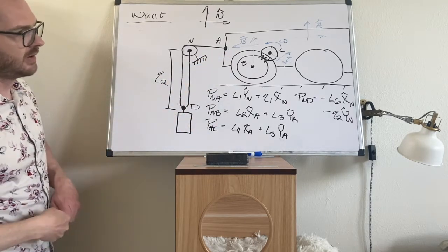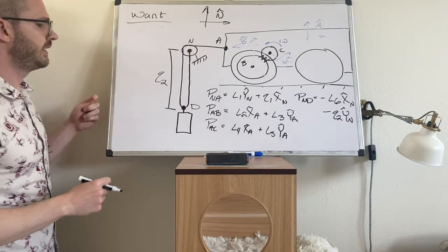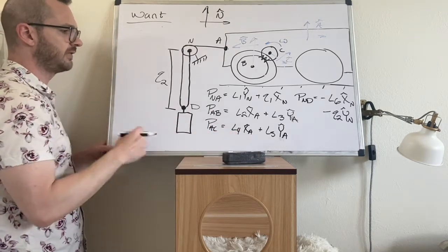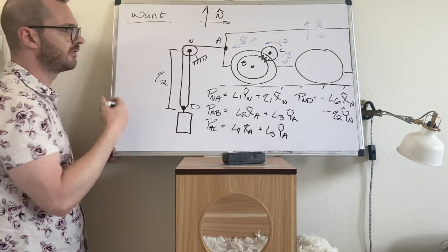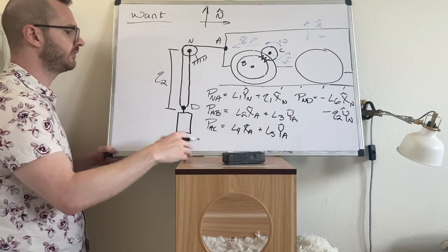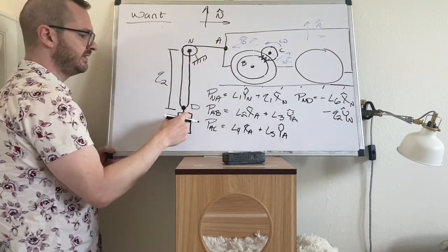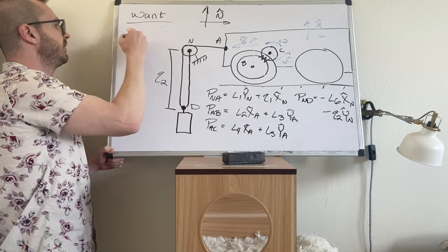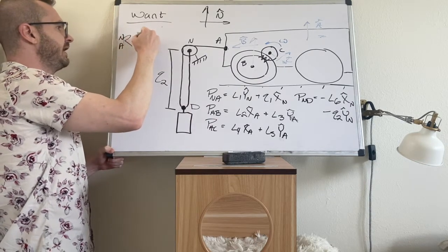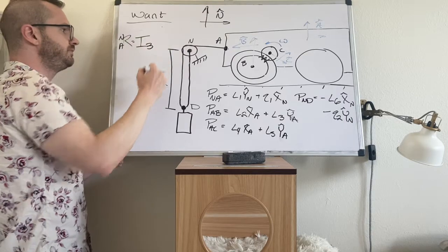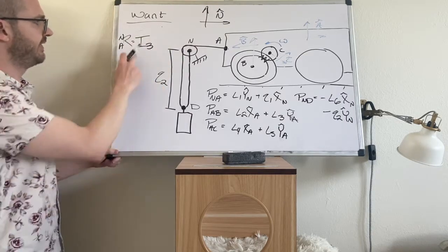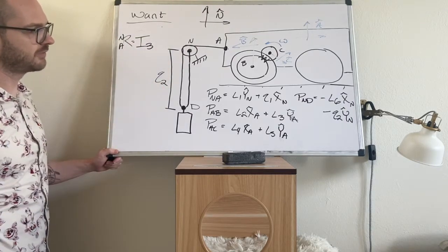All right, so we got the position vectors. Let's do the rotations. I'm going to do my shorthand for the rotations because we've done it so many times. So A frame does not rotate, D frame does not rotate. I'm going to do R into A, and I'm just going to say that this is an identity matrix.